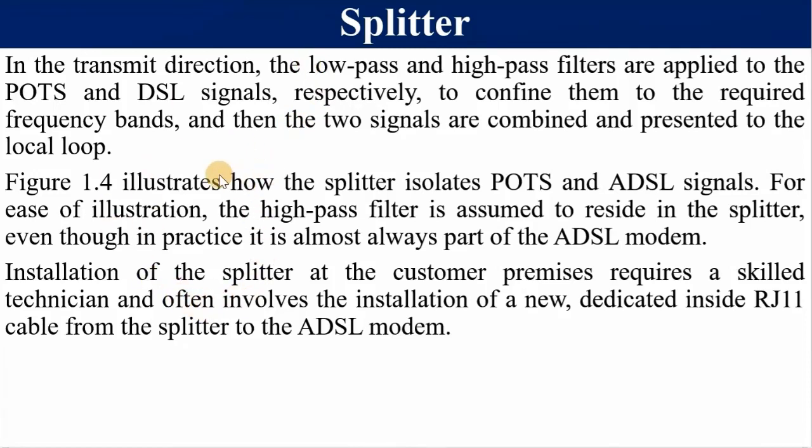Then we are going to have a look in the next slide to see the way a splitter operates, or how it separates the voice signal, which is the plain old telephone signal, from the ADSL signal. And please take note of the following assumption. We are assuming that the high-pass filter is inside the splitter and not in the ADSL modem. And the installation of the splitter at the customer end requires a skilled technician, because you can swap the output ports, and if you do that, the phone will work, but the ADSL modem won't synchronize with the one at the exchange.